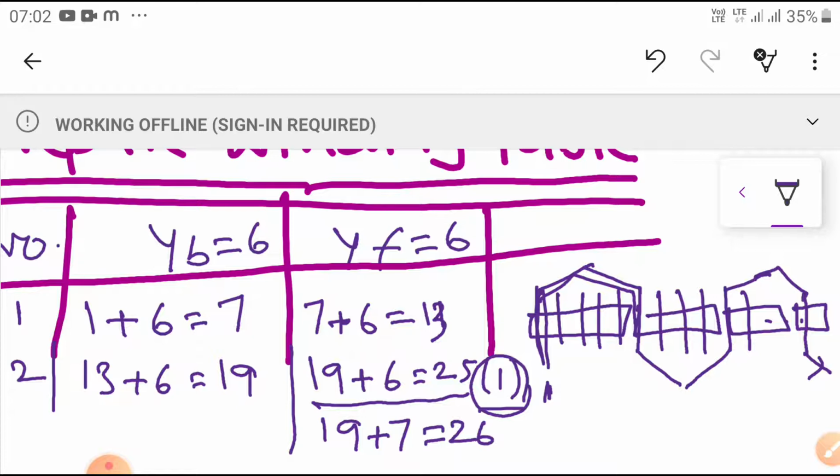If one side of the coil is placed in slot number 1 previously, the other side of the coil should be placed in slot number 1 plus 6, that is 7. The finishing end of the coil side at slot number 7 is connected to the starting end of the coil side at slot number 7 plus 6, that is 13. Now the other side of the coil side at slot number 13 is placed at slot number 13 plus 6, that is 19.